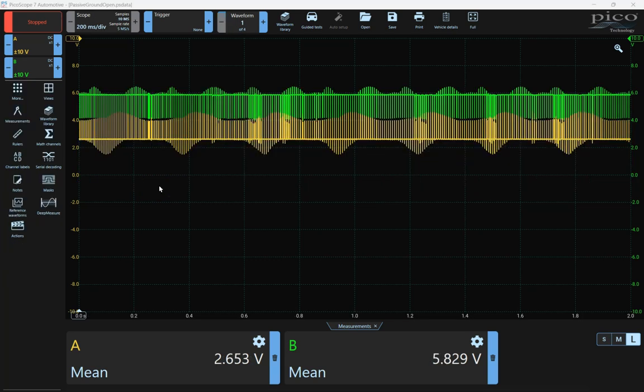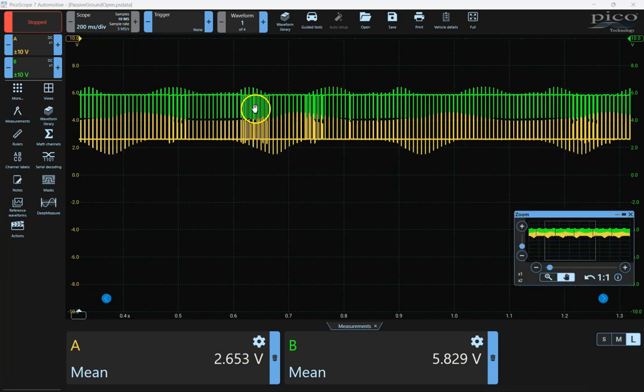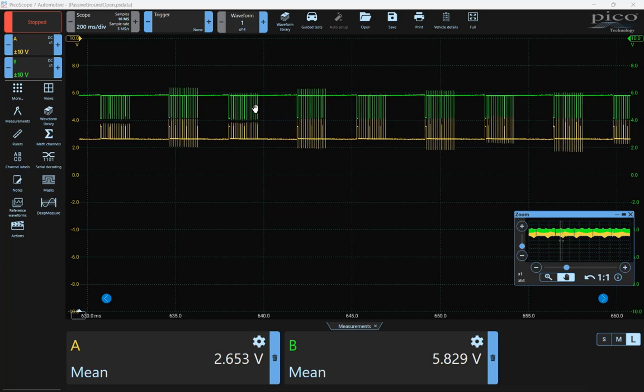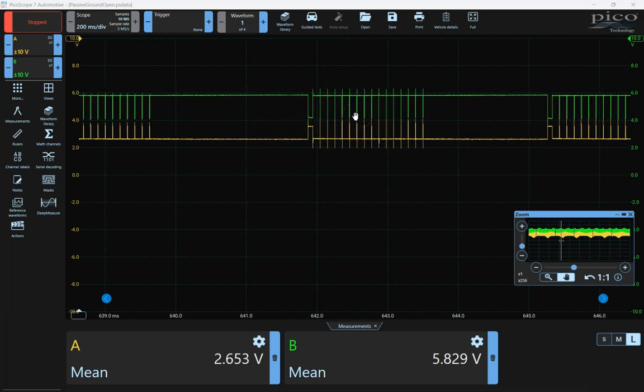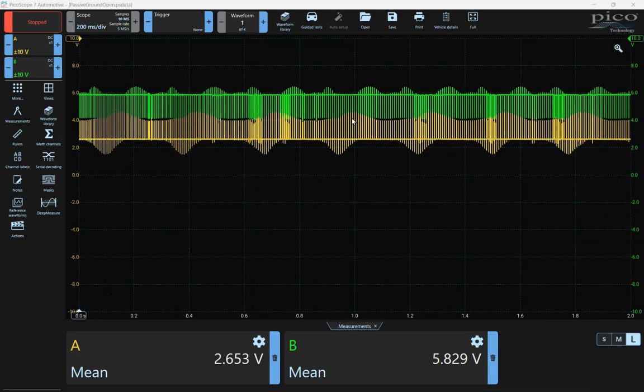So in this case, this is on a real machine. I removed the ground terminal from the so-called passive active terminator, the terminator that only has 4 wires. Therefore, it doesn't have any power. And you can see what this has done to the CAN bus. This is garbage. I can't do anything with this.